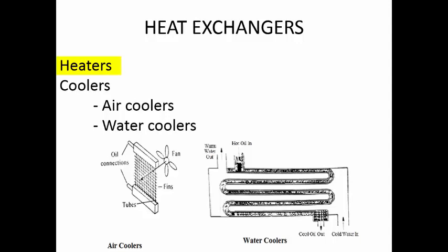Now, if you do not have any agitating or mixing arrangement, then the hydraulic fluid that is very close to the heating coil will have its temperature rise very much as compared to all the surrounding fluids. If the temperature rises beyond a particular value, then it may catch fire or it may get oxidized. That is also possible. So whenever you are using a heater like a coil, you have to make sure that the fluid is continuously in motion. Otherwise, the fluid very close to the coil will have its temperature increase beyond acceptable levels.